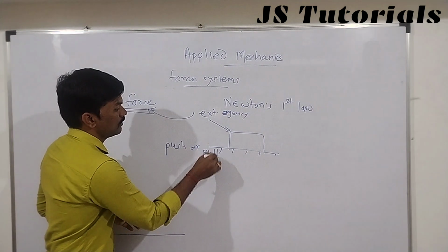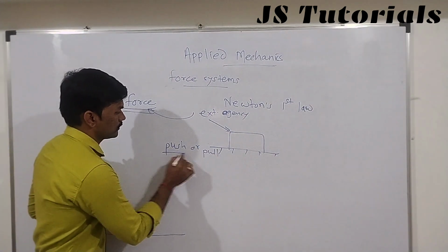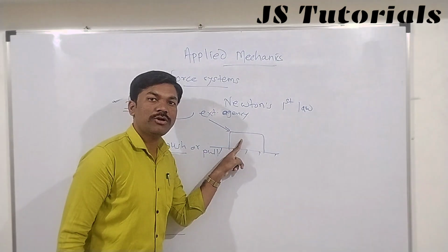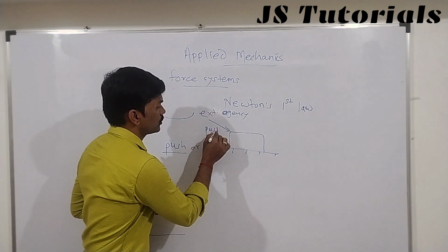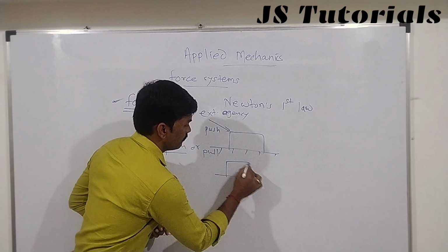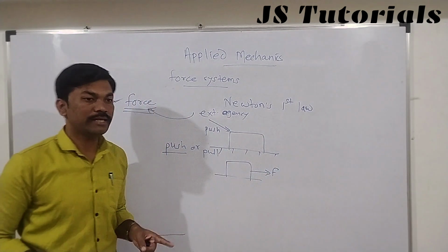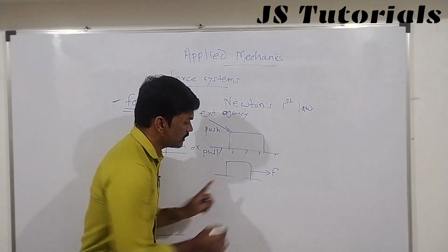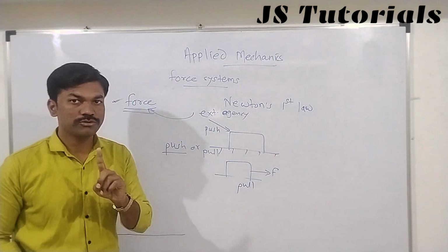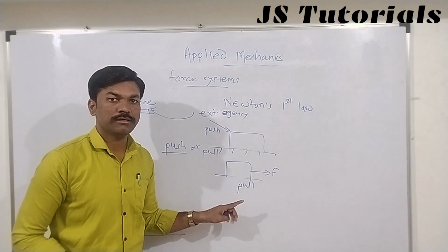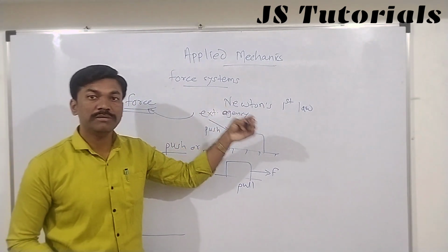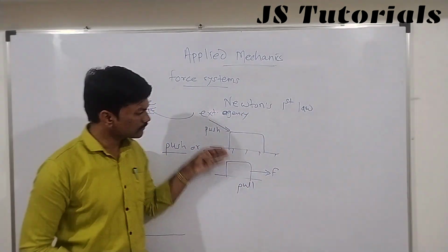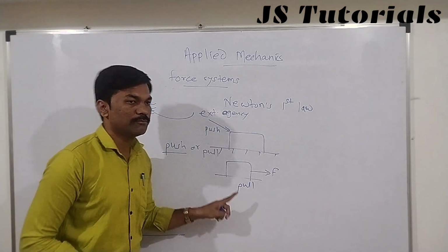Either push or pull. What is meant by push? Here, the force arrow is directed towards the body. This is the concept of push. And in this case, where the arrow is acting away from the body, this is the concept of pull. Students should remember this push or pull concept, which is very helpful in the beams concept for finding the reaction, or in the resolution concept also.